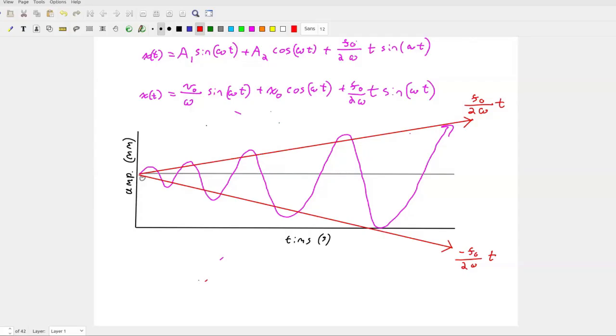So if this was true and something went into resonance, it would always fail. What's missing in this system that's missing in all real world systems? No damping. If we add damping, we can constrain the resonance, maybe into something useful, right? But if we don't have damping, everything once you get it excited at the right frequency will fall apart. And if you keep it excited there, it does take time to grow.